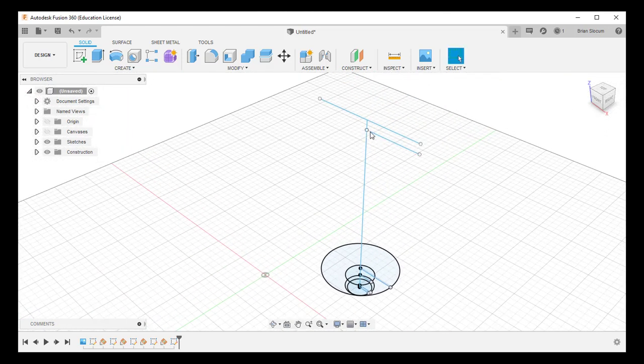Okay, we have one more profile we have to build. It is the top of my object, but this time it is not going to be a circle because we flattened that tube. So what I'm going to do is create a rectangle on a plane that goes through this line, and that rectangle is actually going to be this length, so it comes out to here, because I referenced that, and then I took my calipers and measured the width of that rectangle. It's about 1.5 millimeters wide. So we'll do that next.